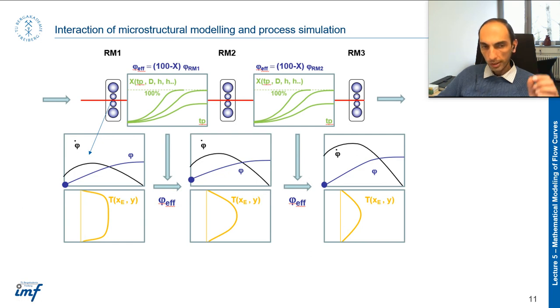So the flow stress in the simulation or in reality cannot be just a number. It should be temperature dependent, strain rate dependent, and strain dependent, at least if we look at the matter from the process point of view. And from the material point of view, we should consider the dislocation density, precipitation hardening, and other phenomena we talked about before.